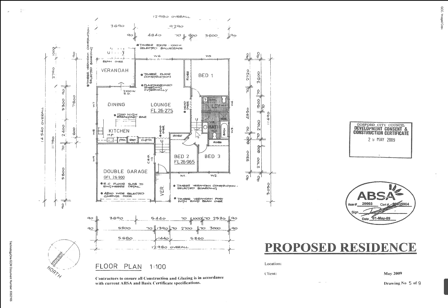So the stairs are always supposed to be shown with an arrow pointing to the direction that's going up, and they would be numbered at the bottom. The rises, the vertical face of the steps, would be numbered 1, 2, 3, 4, etc., heading upwards. Okay, we've got a timber floor construction, plasterboard sheeting internally, it's all standard. We don't have any information on paint finishes and things like that because it's not worth showing here, and it's a variable.